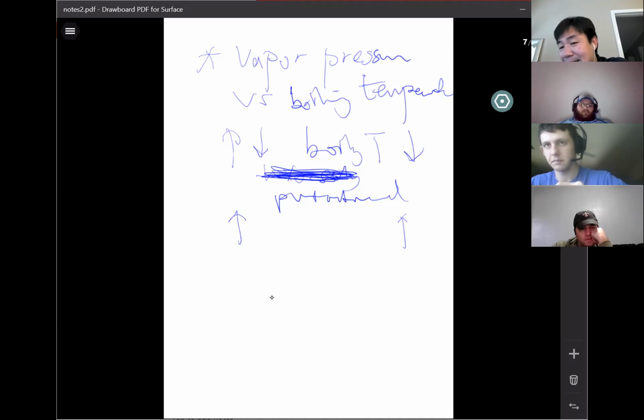It's a fully 100% filled pipe. Where is the volume? You don't have the volume. That's why you have a very violent process in there. The vapor tries to make a volume, but you don't have it. It causes vibration, and it causes damage to the facility and equipment in the long run. Not even the long run, in the short run, it will damage it if cavitation happens. So the boiling process is very bad.